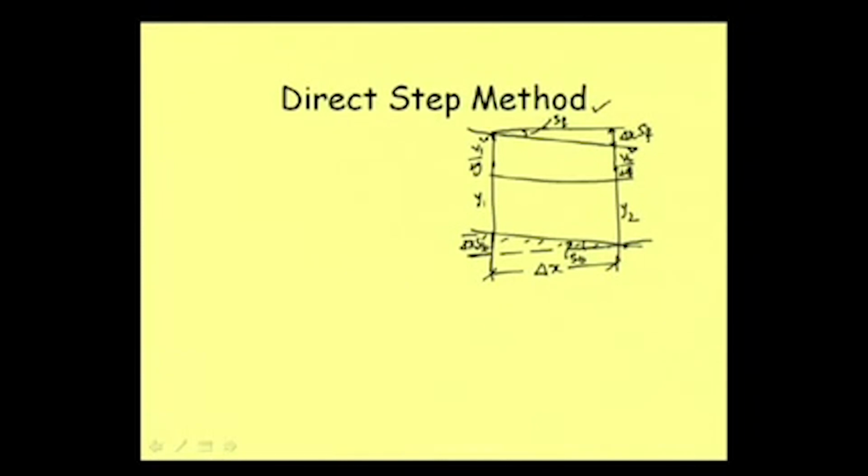Well, so the energy level between two sections we can write in this form. Here we are of course considering the loss part as delta x into SF, and we are considering that the loss is only due to frictional loss. And the energy slope is also drawn like that. This is the energy gradient line, okay.